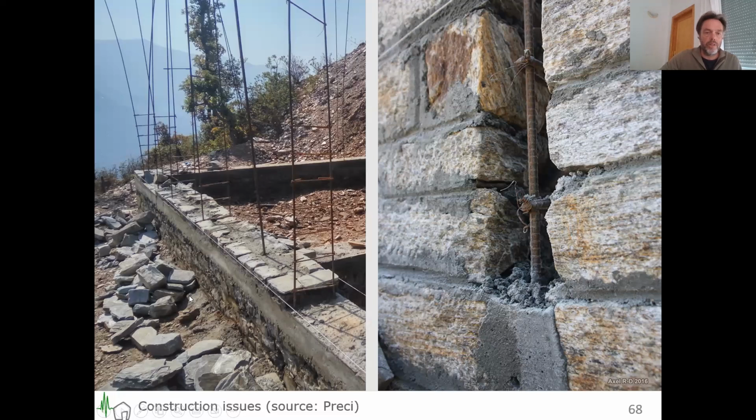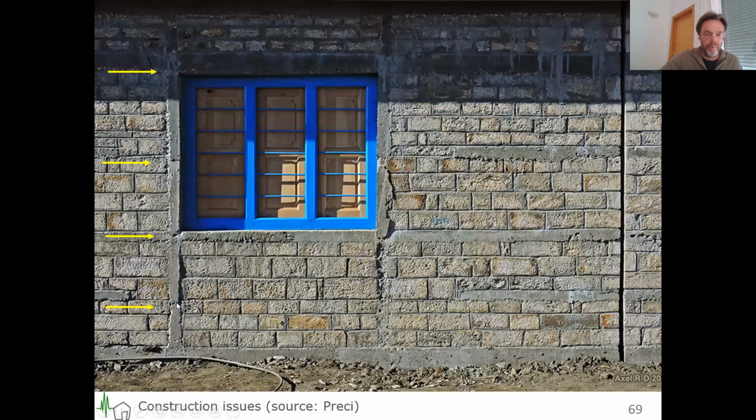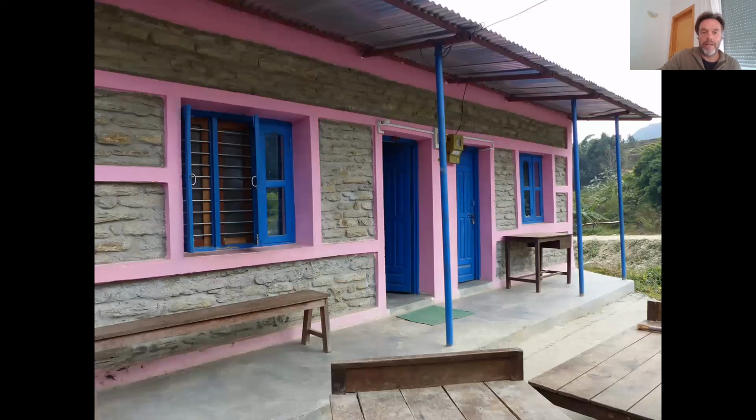And then when they start casting the concrete in between, they do it at every, I don't know, 30, 40, 50 centimeters height, and it is already pre-cracked before we have started. So it is almost impossible to properly make all these little connections. And so you get concentration of forces where you don't want it, you get a very weak frame, it's not helping. And the question is, is it necessary at all? And we saw that in many examples.